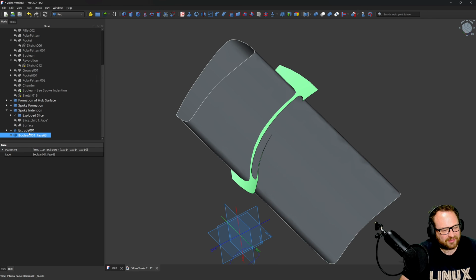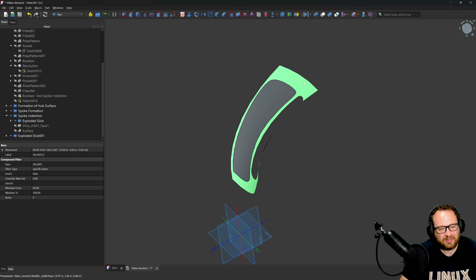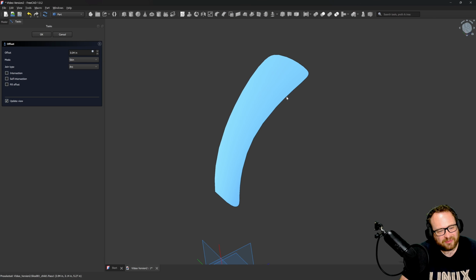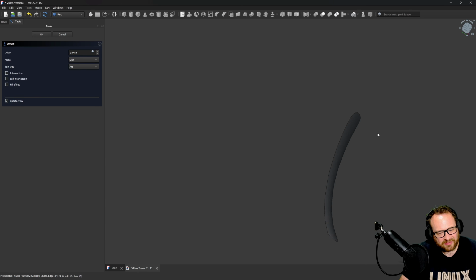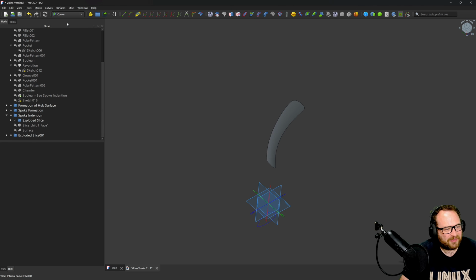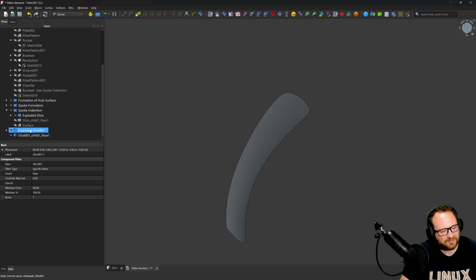It's probably best to select that from the tree, right? So we'll select our Boolean and our Extrude, slice apart in that order, and delete the face that I don't want. Once again, we can try to offset. I don't have that much confidence, not looking good. So we'll do our fallback here and head back to Curves. Select this face and create a face from the sub shape.